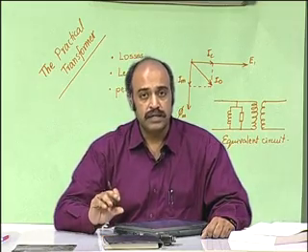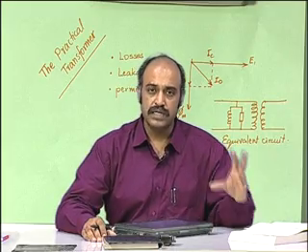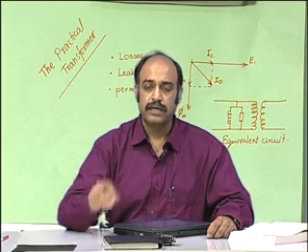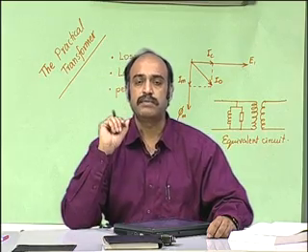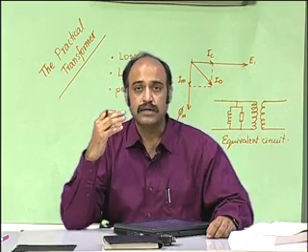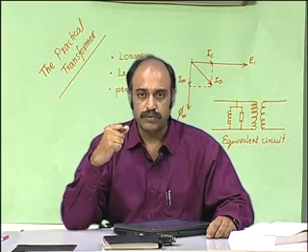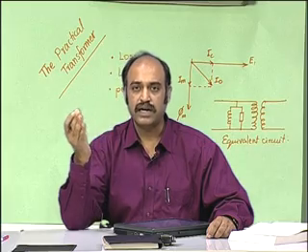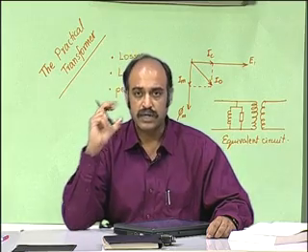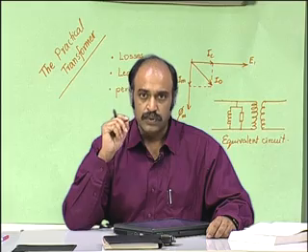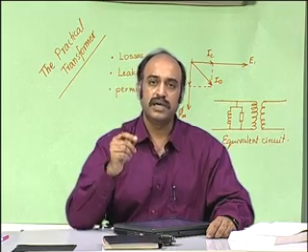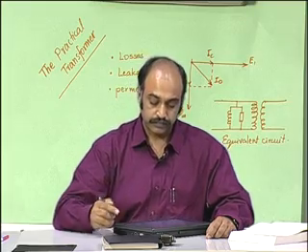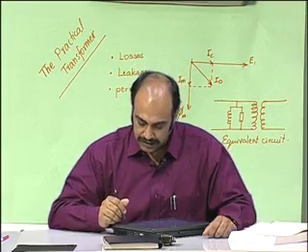In other words, if there is no load on the secondary, if there is a voltage applied on the primary, there is no current flowing through the primary winding, 0 current is sufficient to set up flux in the primary and flux in the core, and the flux that is set up in the core, which is the motive force set up in the core, will induce an EMF on the secondary according to the turns ratio, and a secondary voltage is developed, with 0 energy being lost in the hysteresis or the eddy current or the copper loss. That would be the feature of an ideal transformer.